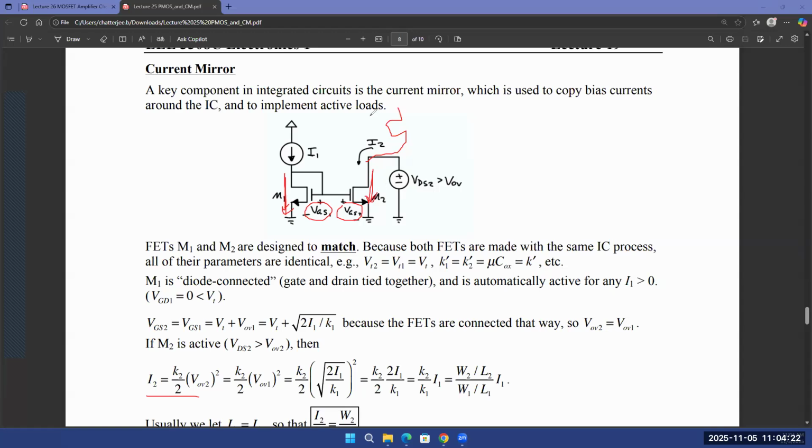So if you say that I connected another transistor in series on top, and that effectively changes the overall resistance looked into this path, that is true. The overall resistance seen by VDD is changing. And if you change the W over L ratio of the top transistor, the overall resistance seen by VDD will change. However, this is the beauty of it, that the current does not depend on the resistance. Now it becomes an exact copy of the left side current. Irrespective of the resistance that you have, the current becomes a copy of the left side. So it becomes an actual current source.